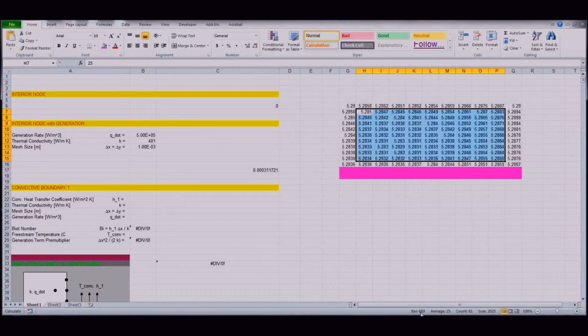And what you're noticing down in the bottom here, you see the number of iterations. It's kind of slow, and the reason is because we're watching it. If you scroll down and don't watch it, and we'll do that in the next run, you'll notice that it moves much, much quicker. So we'll let this one do its thing. It's trying to converge. And so what it's doing is it's going through calculation after calculation, applying the finite difference technique. An iterative convergence process is what we're essentially doing here.